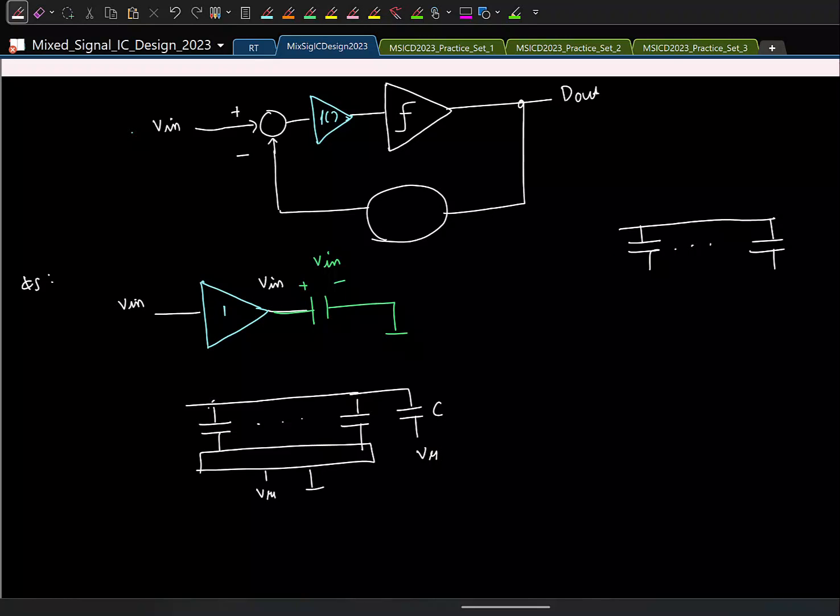So now this will generate the reference voltage. And what do we have to do to the reference voltage? Should I feed the reference voltage directly or should I do something? I have to buffer it. I have to use the same buffer, right? So what I'll do is this. Same buffer. Now in principle I can give it to the comparator.